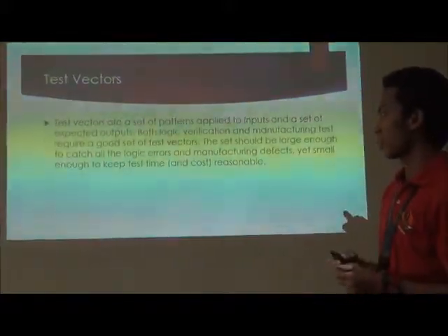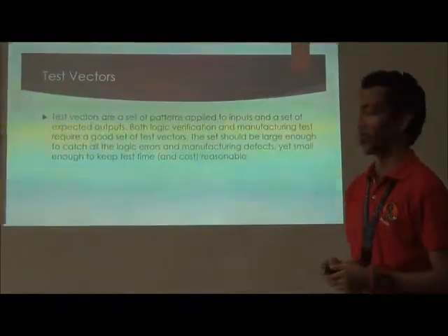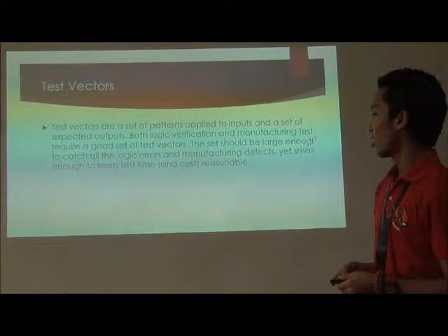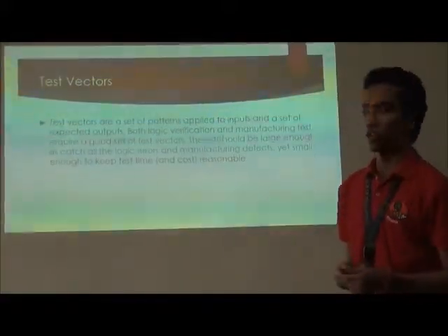So both logic verification and manufacturing tests require a good set of test vectors. The set should be large enough to catch all the logic errors and manufacturing defects, yet small enough to keep test time and cost reasonable.